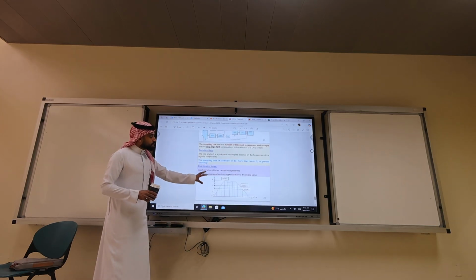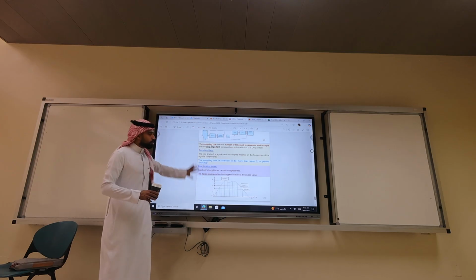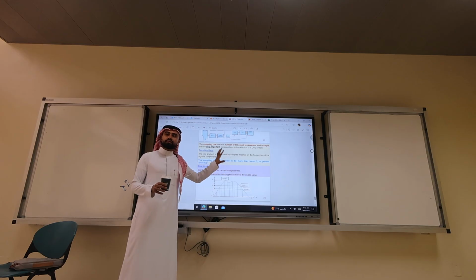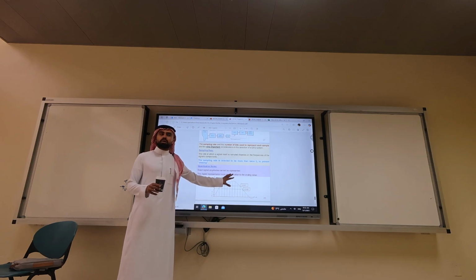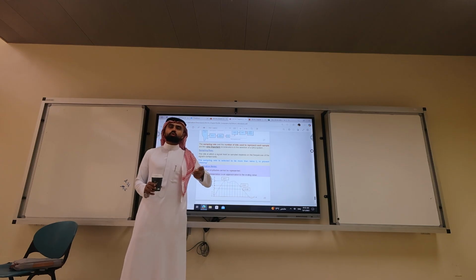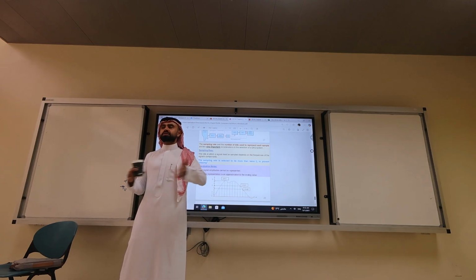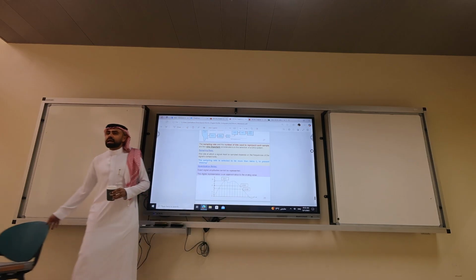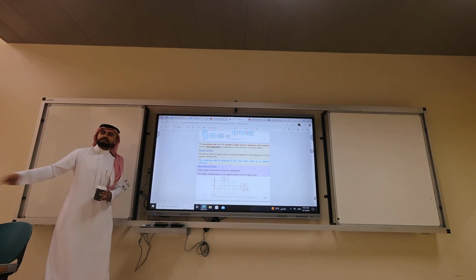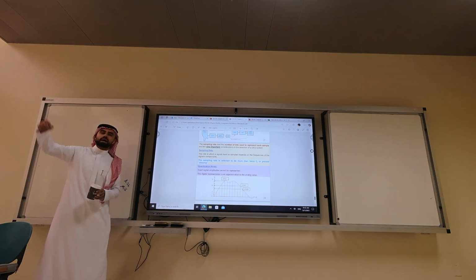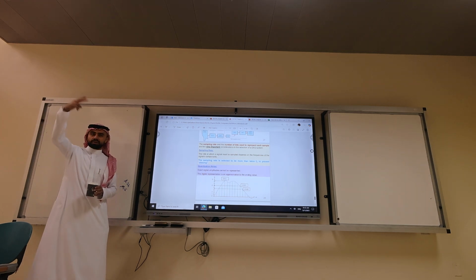With the analog to digital converter, the only information I want you to know is you need to have enough sampling frequency. You have to take enough samples, twice as fast as the largest periodic signal. So if you have, for example, an electric motor that spins at 60 Hertz, you need to take samples higher than 120 samples, twice the frequency.